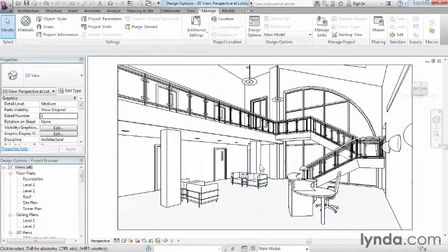I can now select all of the original elements in the main model, and I can no longer select the railings. So when you're in design options, you have to decide, are you editing the main model or are you editing one of the options? Now notice that the glass panel railing is what's displaying on screen. We'll be talking about the primary option in more detail in a later movie, but the reason that the glass panel railing is what's on screen when you're editing main model is the primary option is what we typically see in main model.